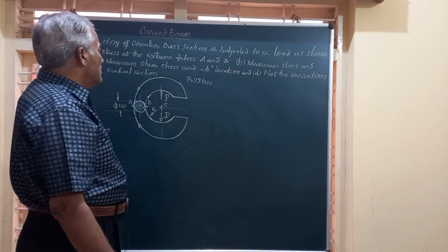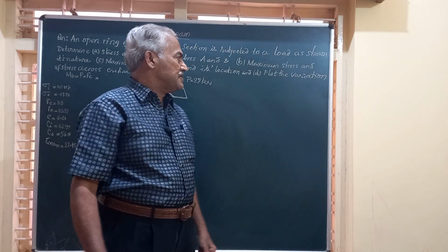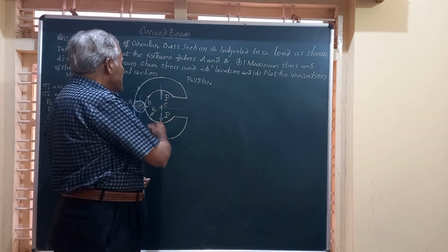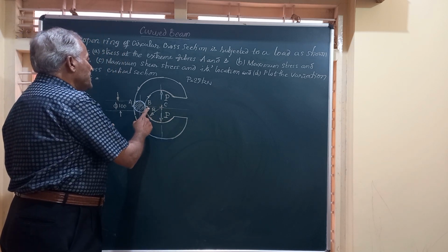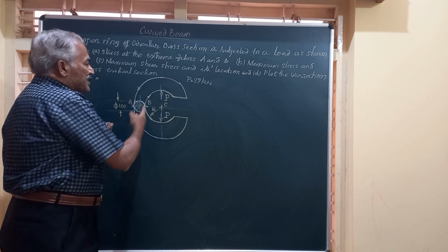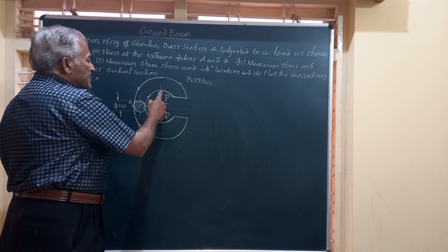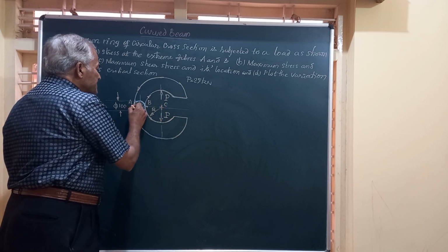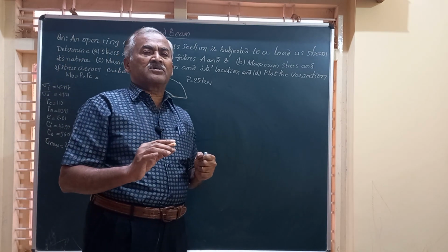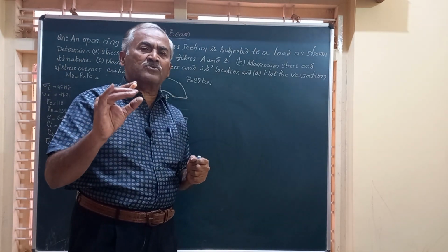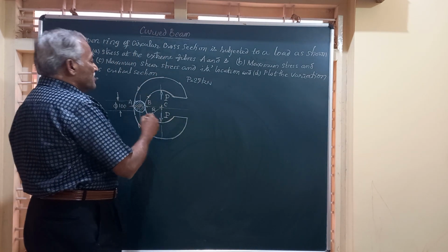Friends, in the machine design data handbook, if you refer to, there are equations which will give you the value of stress at B and at A. And I have shown here the cross section is subjected to a tensile load. So across this cross section AB, which is called the critical cross section, that is the cross section which undergoes maximum stress, is given by this formula.